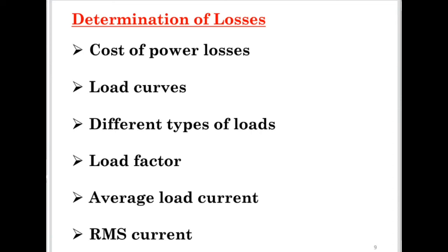If I consider that 2 megawatt was consumed in hour 1, 2 megawatt in hour 2, 2 megawatt also in hour 3, hour 4, and hour 5, meaning the consumption is not varying. So when the load factor is 100%, the consumption is not varying because average is equal to maximum demand.